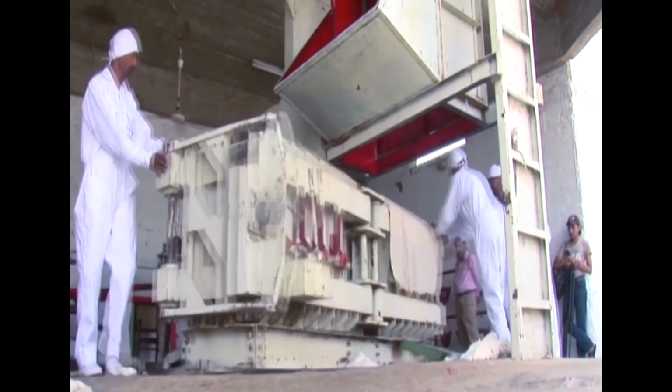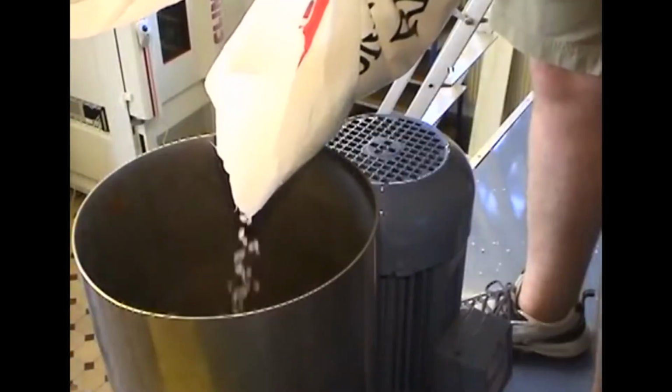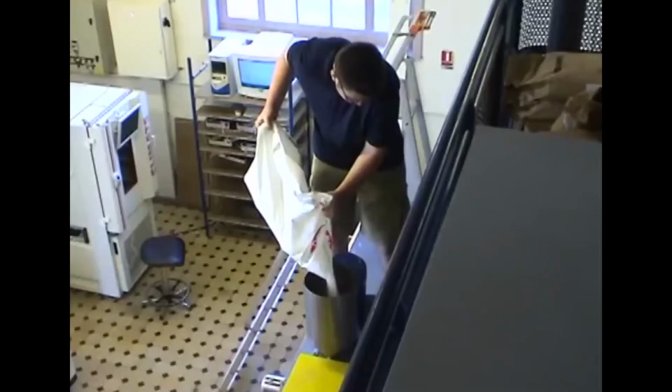When they are blended with other fibers, they are cut into smaller staple lengths and then blended with the other fibers. These manufactured fibers have different polymers. So, the polymers are being produced and they will come to the chemical spinning factories in the form of chips or in the form of powder. And so, these chips and powder should be made in the form of a liquid, and then the liquid should be made in the form of a linear polymer, so that it becomes a filament.